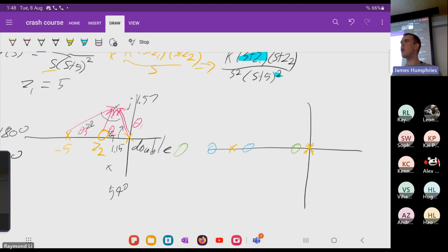I can put these two zeros wherever I want because I will end up with an expression where I have two unknowns to one answer. And then I can change one of them to be whatever I want. Therefore, to make my life easier, because there was also a double pole here, I just put one of them here. I could choose anywhere, so I put it at a location where it cancelled out a pole. Then I was left with 3 poles and 1 zero I could move. Make sense?